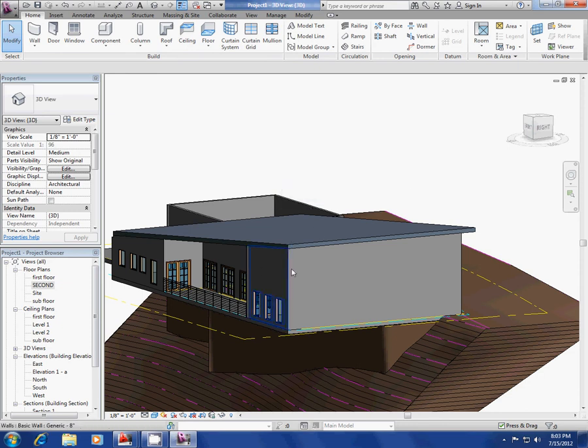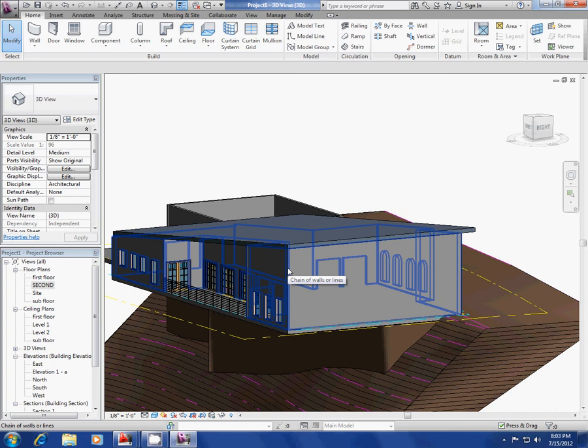Oh, if I just hover over a wall and I know that there's a string of them, I just press tab and it'll select all of them. And that works a lot with, I mean, the tab button does many different functions. It just depends on what component you're working with. So say like with the dimension string, if I press tab, it's going to snap to different materials or different components. If I'm selecting a wall, it'll select multiple walls, or it'll select even different walls.